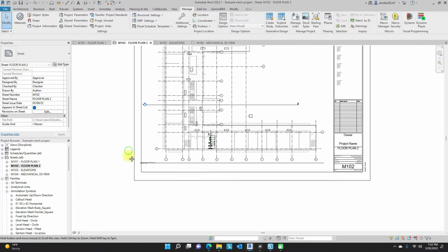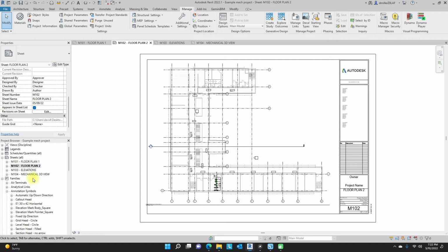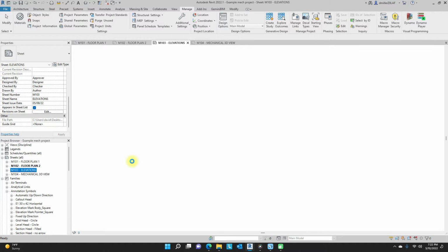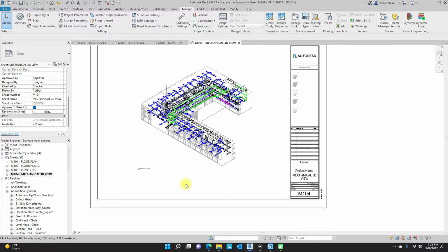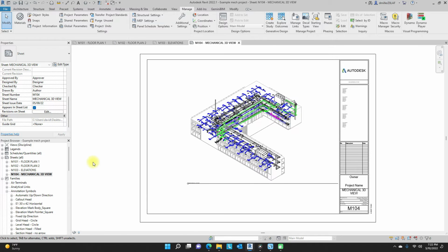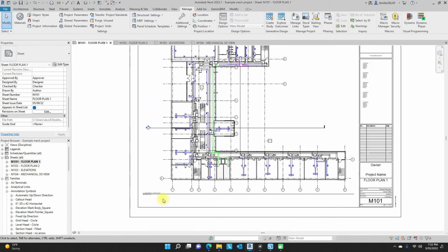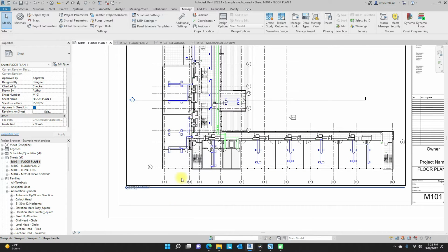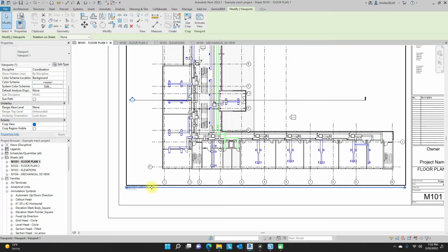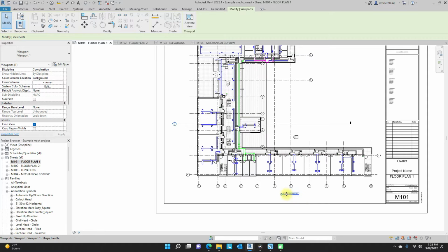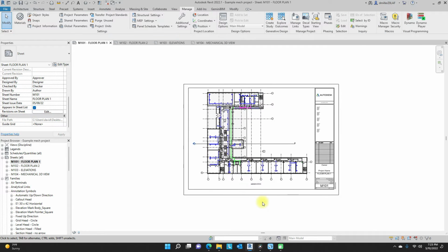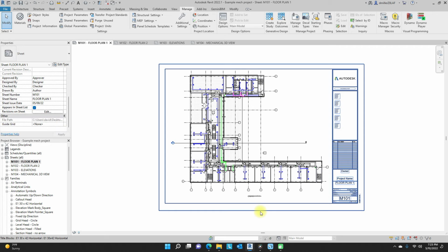Here in Revit, I have a sample project comprising of a series of sheets that include some floor plans, elevations, and a 3D view. Each view type has a specific viewport title type for it. It is common for firms to have a standard where the view title is centered on the viewport and the title extension line is the same length as the text. Prior to Revit 2022, this was mostly accomplished by manual efforts, but now we are able to control this programmatically.